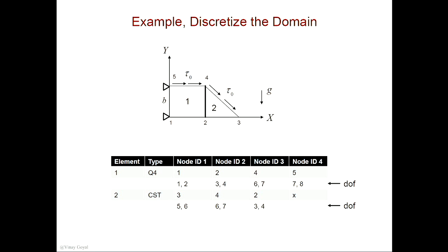The second problem, I think, is a bunch of triangles, isn't it? But if you look at that problem, almost all those triangles have about the same shape, so when you calculate integrals, they're all going to be very similar to each other. If you number the elements correctly, and number the connectivity in a smart way, you can get it so it looks the same, except for two triangles at each of the edges.